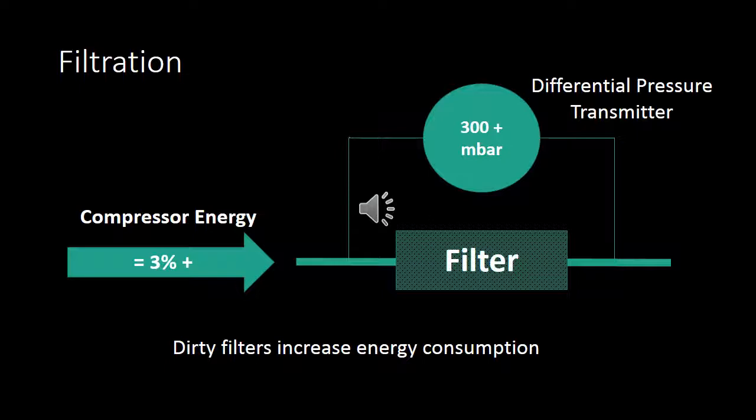As the differential pressure increases, the percent of power consumed by the compressor to service this pressure drop will go up. The cost of new filters can be compared to this additional power cost. The filters can be changed when the power settings justify the new filter costs within the required time period.